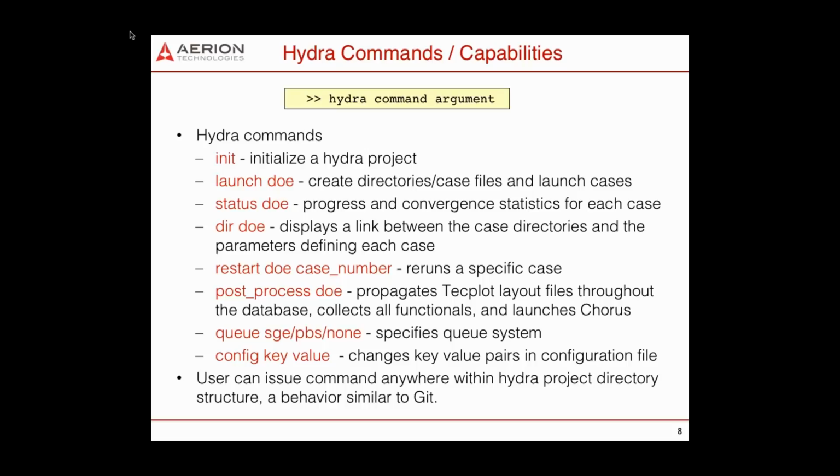The first thing you would do is type in init, and that will initialize the Hydra project. Then you'll type in launch, and that will basically create the directories and case files and launch all the cases in the database. There's some status and dir commands, which will allow you to assess the progress and convergence statistics for the cases and display links between the case directories and the parameters used to define the case. One can also restart to rerun specific cases in the event that things fail.